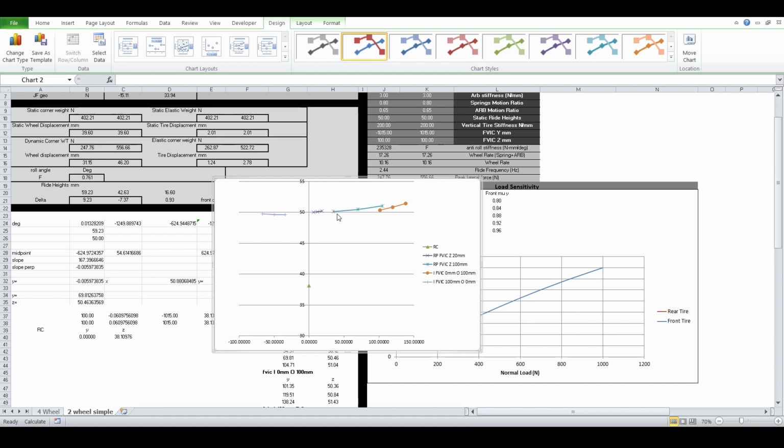So this is showing the roll location of how it changes. So it's 50 millimeters up, and then it moves to the outside. So 0 center line, and it's moving roughly 100 millimeters to the inside. So remember, this is positive Y, so that's to the left. And then for all these, it's simulating a left-hand turn.